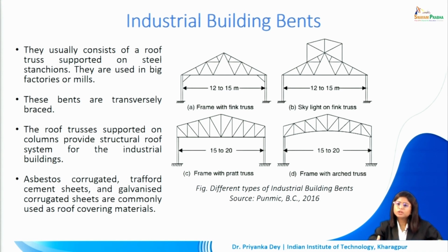So not only for the structural reason, not only for the fact that we cannot have very large columnless spaces in case of timber, the cost of making the members, the cross section of the rafters and the other members used in the timber trusses would exceed drastically, making the overall roof structure heavy as well as increasing its price. So definitely for that purpose, to be able to span a very large gap without the use of any intermediate support, we can definitely go for steel trusses. But in addition to that, it also reduces the fire hazard significantly.